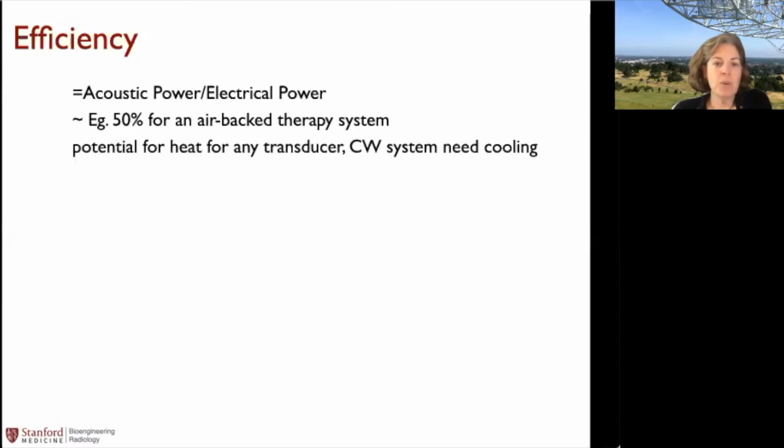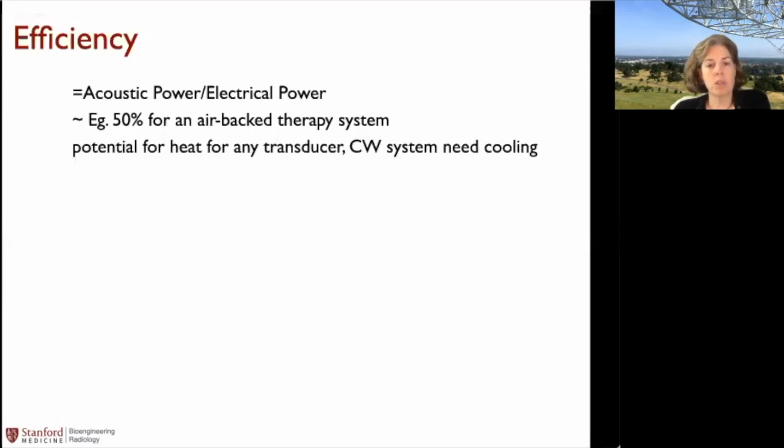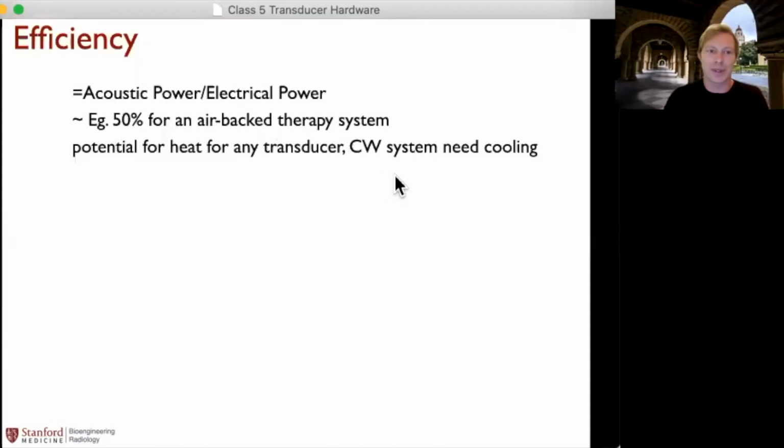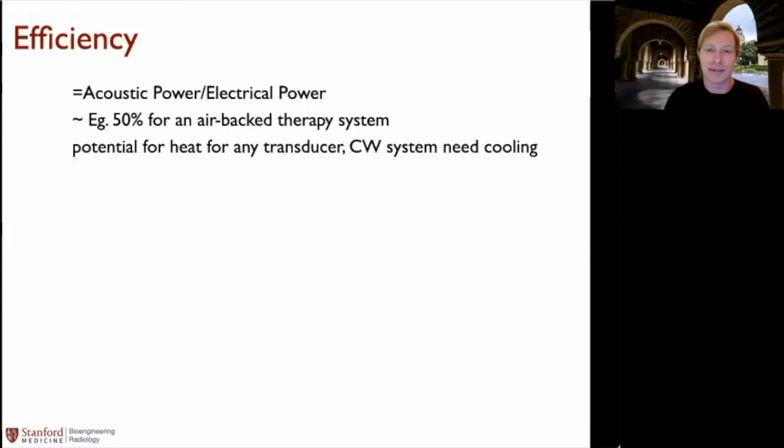Heat isn't necessarily what we want. It's just going to heat up the transducer. It's not going to be very useful. So that's where cooling can come in and play a very important role, especially if you have a continuous wave (CW) system, then you often really need that cooling. If you're going to be driving these transducers for, say, 20 seconds, then cooling can be essential. There's also a sort of interplay: sometimes people will attach heat sinks directly to their piezoelectrics, and then it's no longer an airbag system and you're getting less transmit, but it does help cool the elements much faster.